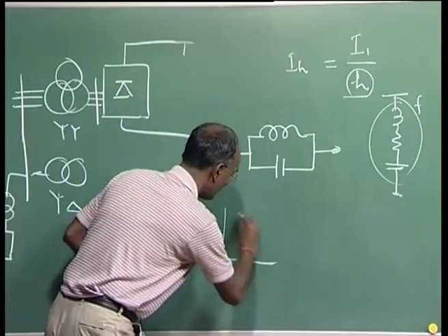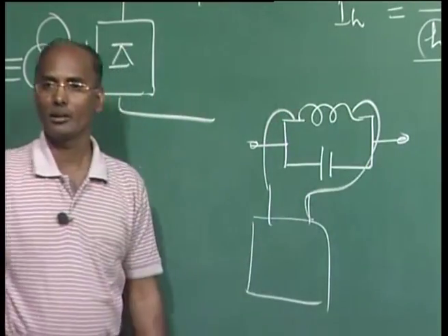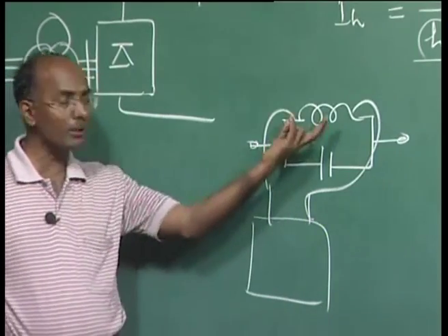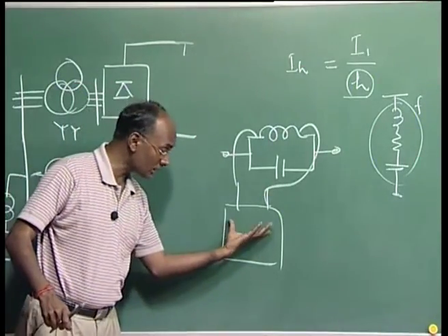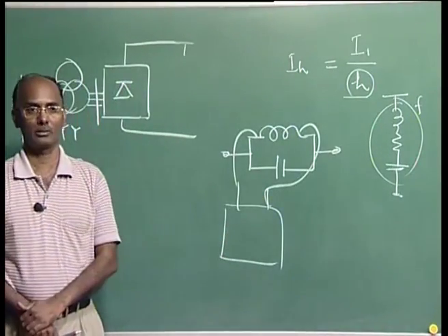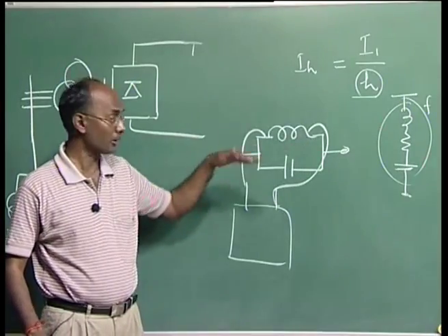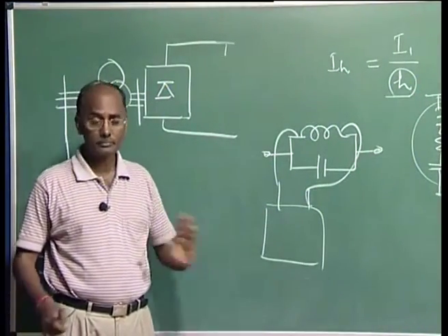This is your inductor, and its 2 terminals will be coming here and here. Electrically I am just representing it as an inductor here, but it is not hanging in the air. It is a huge voltage inductor, so it must be insulated from the ground. So full voltage appears here. This is a 400 kV line, so 400 kV must be insulated.